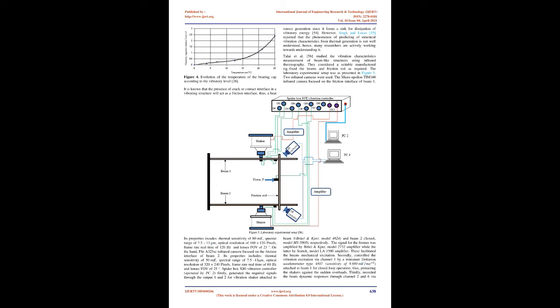[40]. Gao et al. [41] described the statistical method for finding an accurate vibrothermography inspection test procedure for the purpose of crack detection in aircraft engine fan blades. They showed that use of the Bayesian method enables the development of confidence intervals for the probability of detecting cracks. Maierhofer et al. [42] used the lock-in thermography for monitoring damages such as delamination, impact, and fatigue failure in various aerospace materials such as composites, hybrid composites and sandwich structures. They recommended that the use of IRT as a remote imaging system could be advantageous if incorporated in industrial instrumentation to control the entire manufacturing process and for quality assurance.